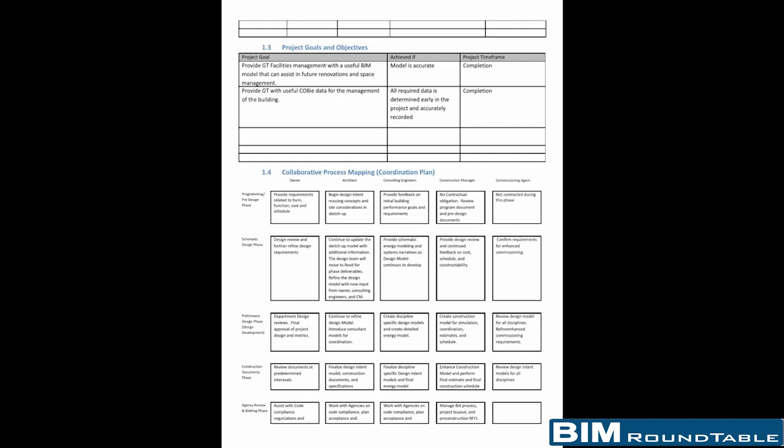I'll show you the shared parameter. I found this nice little shared parameter manager plug-in for Revit that allows you to do batch shared parameters, like a one-touch button type system, and it's really nice. It's actually on the website. I put that up. You can basically go in, type in all your parameters that you need into an Excel spreadsheet, save that out as a text file, and then when you go into Revit, you just hit the dialog box, tell it this is going to be it, and it applies all those parameters to the family that you have open at the time.